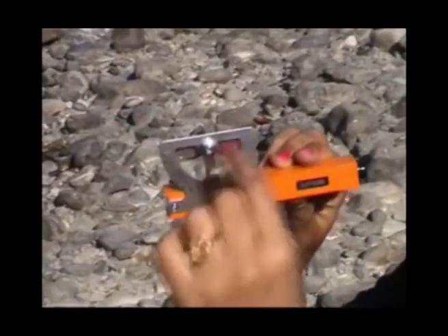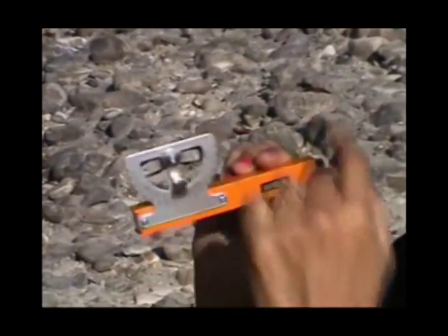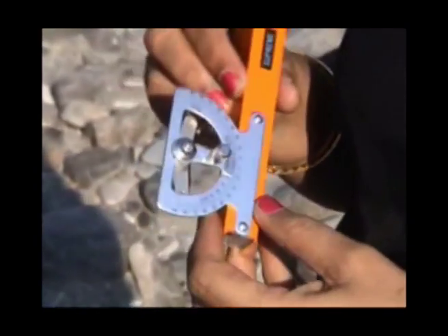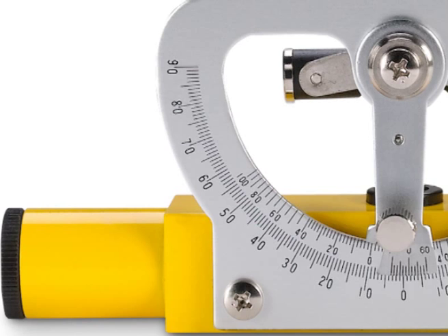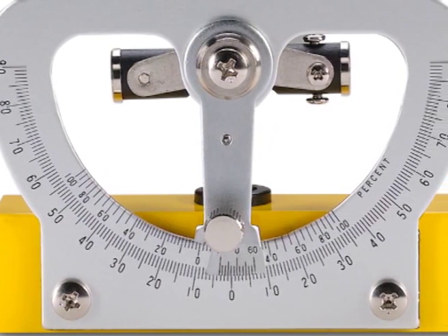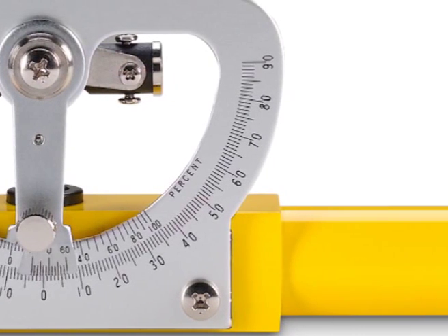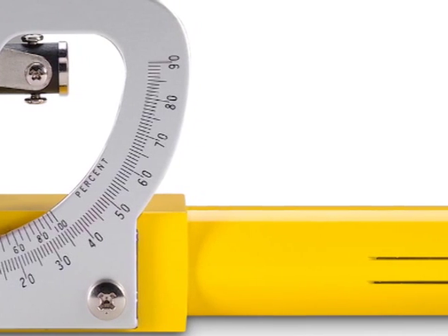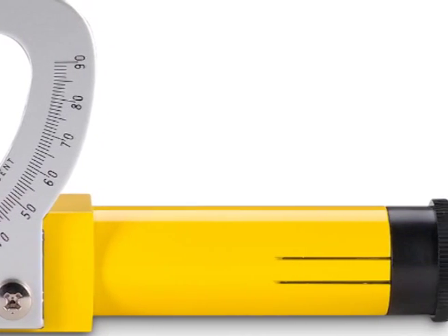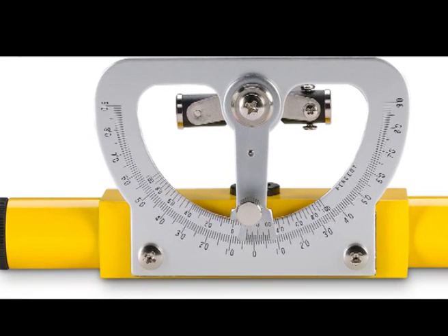Types of clinometers. The Abney level clinometer. The Abney level, like other clinometers, gives the angle between the horizontal and sloping lines. It consists essentially of a telescope T to which a protractor P is rigidly fixed. The middle point of the protractor is marked by a 0, and on both sides of the 0 are graduations ranging from 0 degrees to 60 degrees.